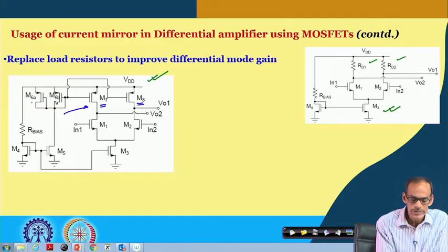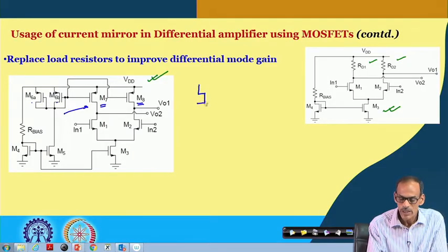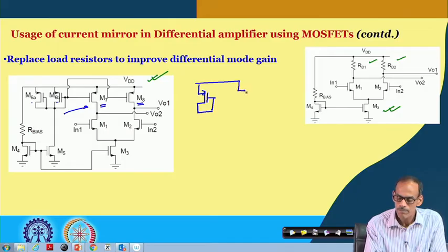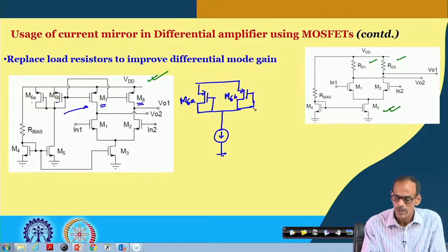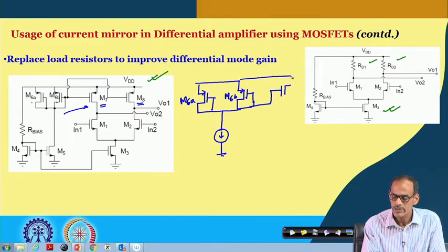So, we have two transistors, M6A and M6B, both diode connected and connected together, and suppose we have some reference current. This is M6A, this is M6B, and then we are mirroring this current to, say, transistor 7.